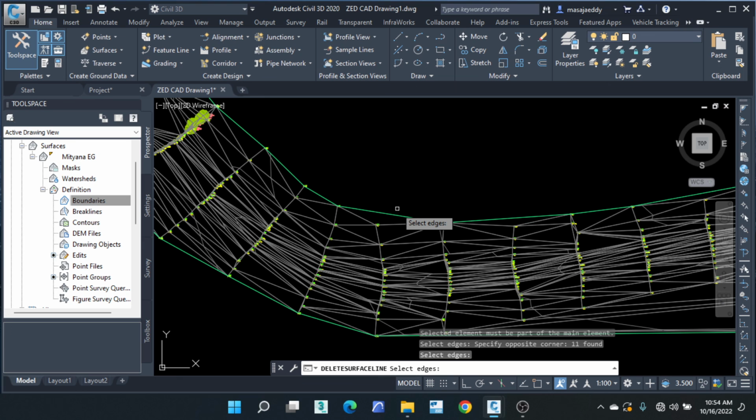Now remember this type that we were choosing. If you remember, we had two types. It only showed one type, but it was an outside, outer boundary, right? It can also be an inward boundary. Imagine a place where points of a surface are collected, and in this area there are ponds, or a lake or a river. They can't go down inside the lake or the river or a pond to pick the points within the water area. So you're only picking points along the boundary of the water, but it's already within the area of the surface. So you can restrict with a border that shows inwards within that area, so that you cut that out.